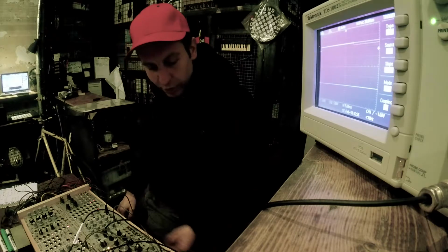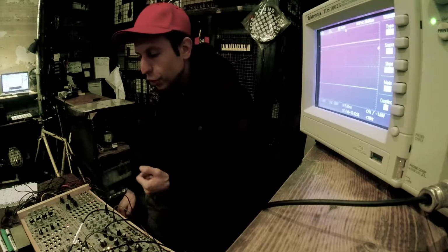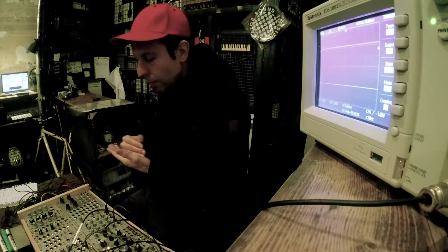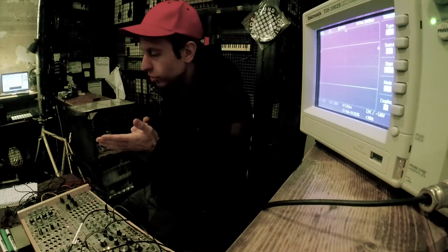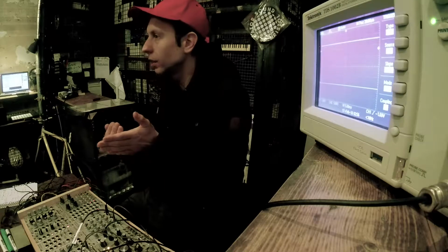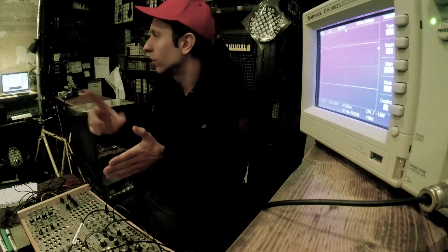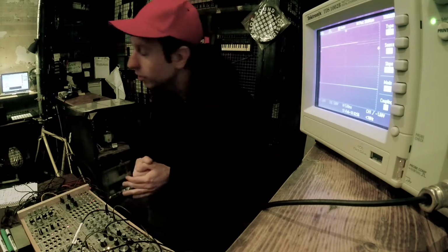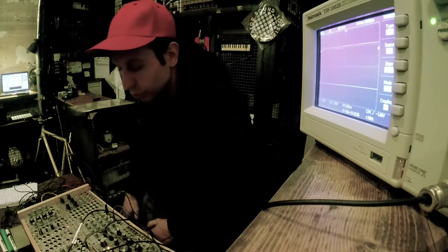Could be a kind of subharmonic thing happening, because normally in a triggered module, if the triggers become of too high a frequency, then it catches every other trigger. So it has a point where it jumps back to a subharmonic of what you're inputting. That can be a useful thing to know.